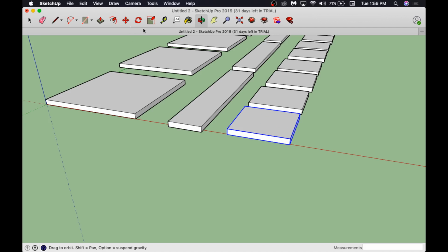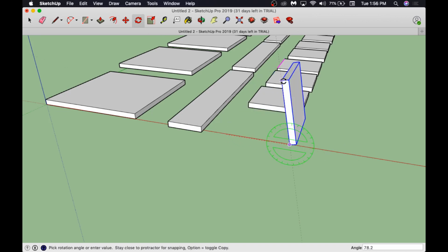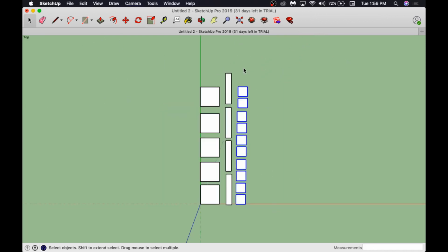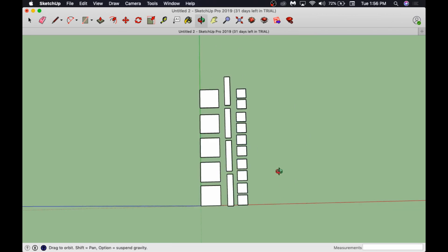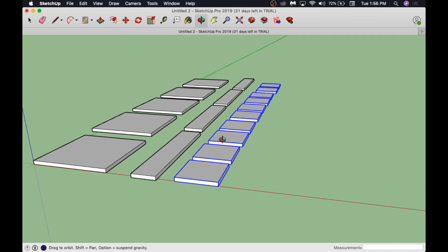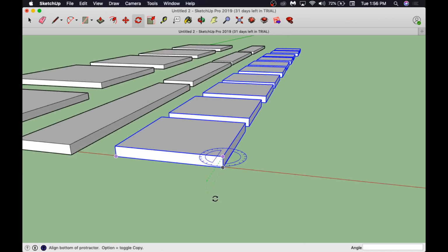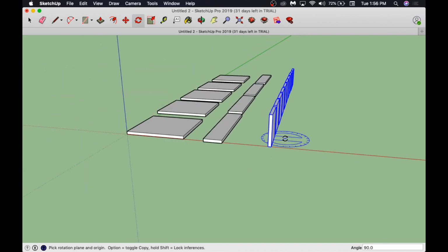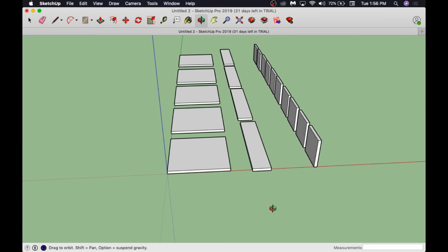So we're going to do this. We're going to press the rotate tool. Just going to look for a face to grab onto. Grab that face, grab that edge, and rotate. However, if you're smart, you will take all of them at the same time. Control 1, select those, orbit. Rotate, get the right axis. Oh, that's the wrong axis. We need to be green. Grab that. Let's snap up. So that'd be a quick way of going about that. Okay, stand them all up and then go from there.